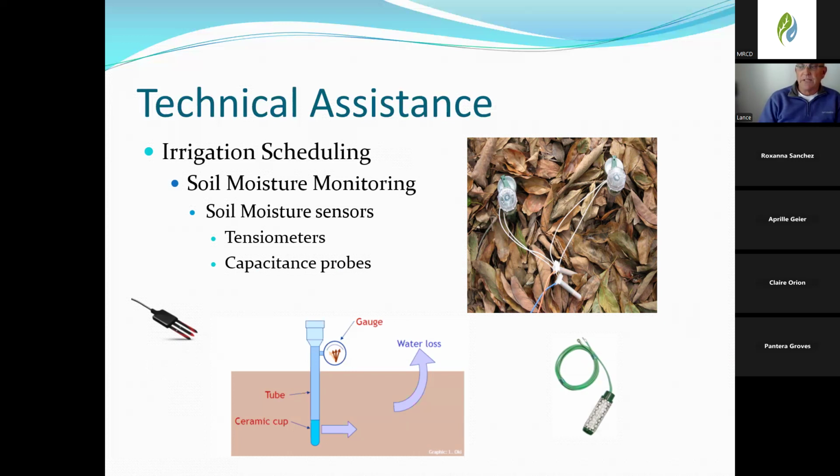So tensiometers, like I said, act like a root. How to use them in making irrigation decisions typically takes about 3 weeks, not very long. But a capacitance probe, while it provides great information, the learning curve is a little longer. It could be 8 to 10 weeks before you fully understand what that percentage number means. That doesn't mean that there's anything wrong with the data. It just means more time is needed to make good irrigation decisions.